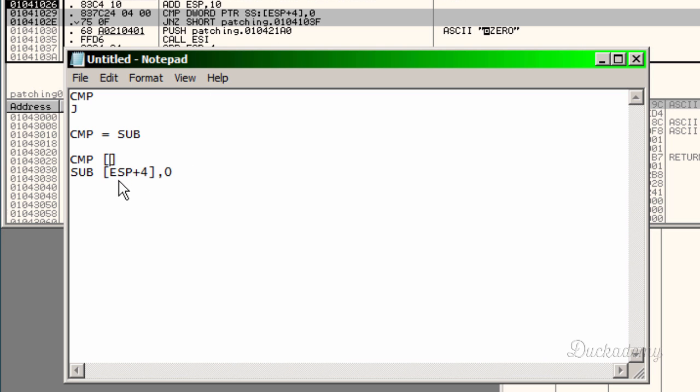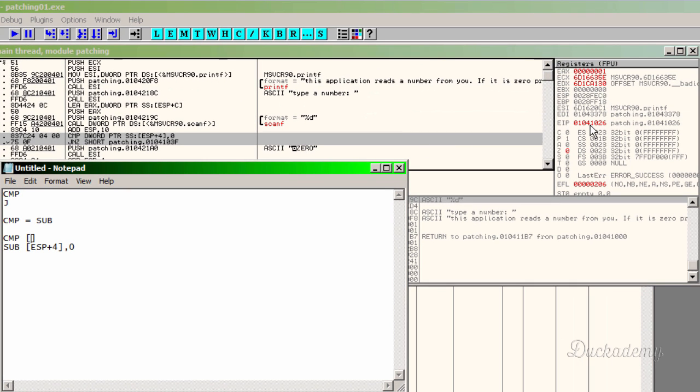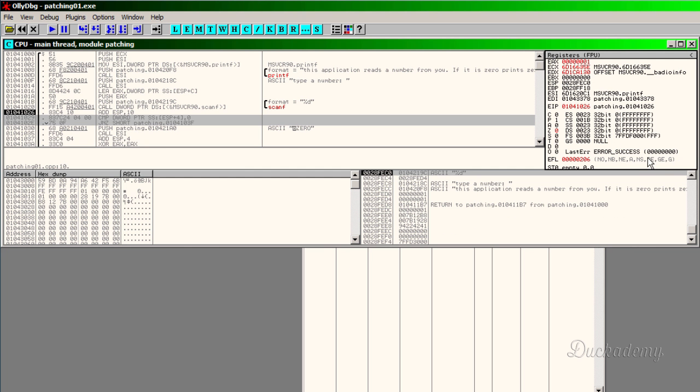But if you use the compare, then it will only modify the flags. It runs like the SUB instruction, but in reality it will not store the result of the subtraction. In the background those are the same instructions, but in case of the SUB, the result is stored. In case of the CMP, the result is not stored, only the flags are modified as if it were done.